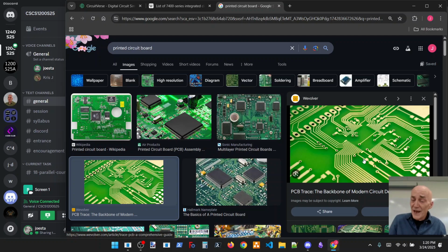So when you took the mask off, there were soft areas and hard areas, and you'd wash away the soft liquid photoresist, and you'd be left with the hardened resist in certain areas. So that then, when we exposed that board to a chemical that would eat away the copper, like a ferric chloride, or now there's a newer one, what do we use now?